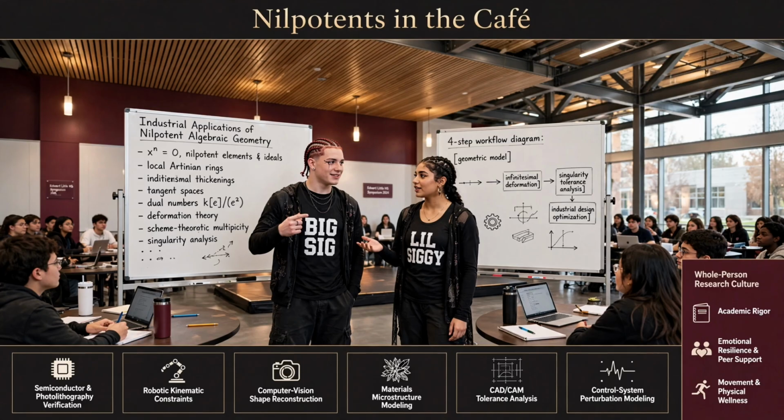Process engineers at massive chemical refineries have to model the state properties of complex, multi-component fluid mixtures. Like, imagine a pipe carrying a high-pressure mixture of methane, ethane, propane, and heavier hydrocarbons all at once. Exactly. And the engineers need to calculate thermodynamic potentials, specifically the Helmholtz energy density, to predict exactly how that fluid will behave under different temperatures and pressures. And calculating that energy density isn't a simple algebra equation, right? It requires knowing how every single variable shifts in relation to every other variable. It requires an absolute avalanche of derivatives.